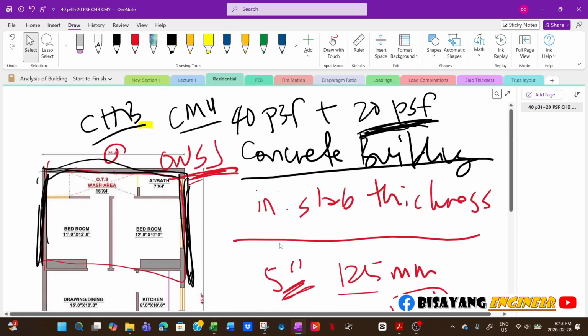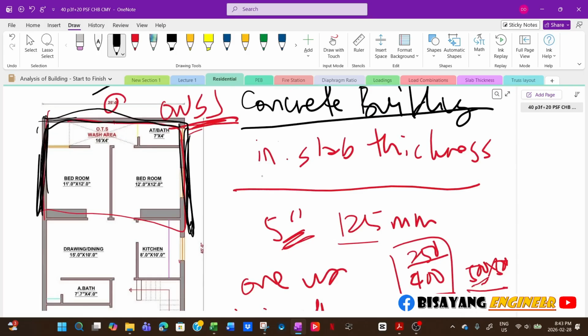So yeah, again, like I said, most of the time it is the architect who will dictate where your column locations are and what would be the maximum size of your beams, and then it is our job to make sure that it works. Say, for example, if the architect wanted this beam span, like clear span, because he doesn't want any column here, like even me, if this is my house, I don't like any columns right here. I would try to have the columns hidden at all intersections.